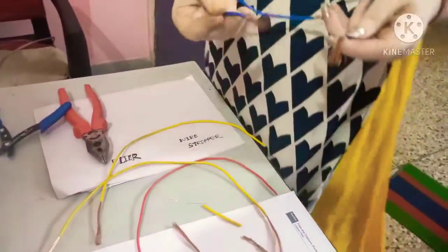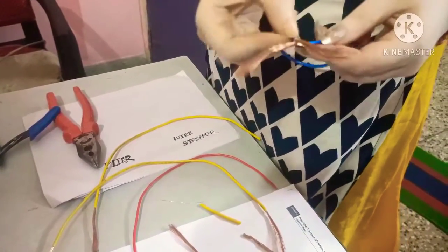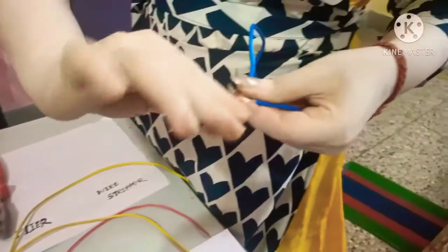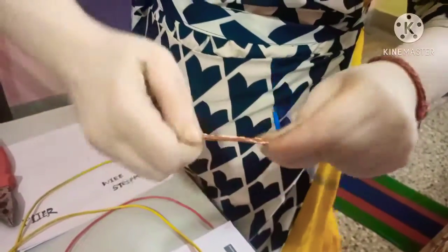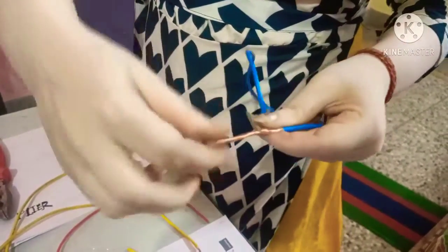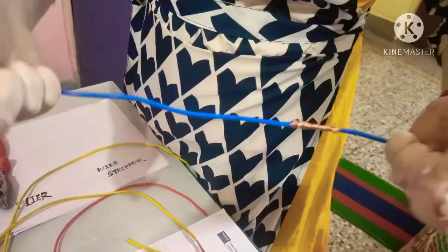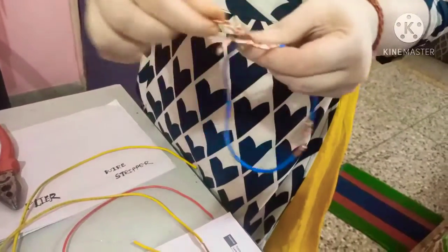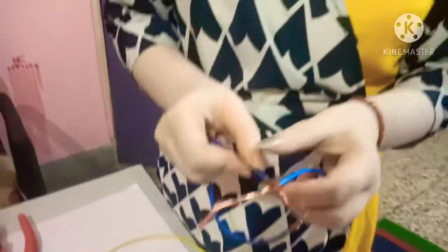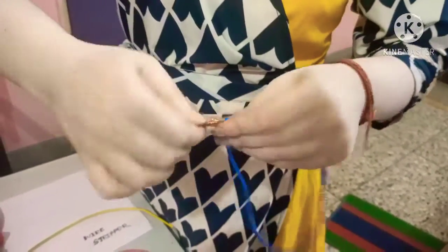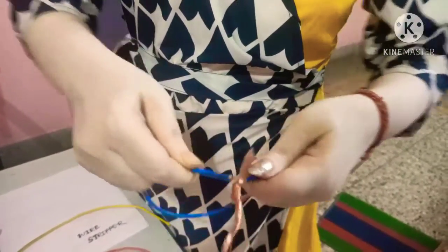So basically we usually take these two wires which I have already stripped. I am trying to join in this way. Just twist it. What is the problem in this twisting? If you are using this method during installation, if you stretch it, then see, it just opens. Whenever you are installing, you should make sure that both the wires are safely joined, so that when you try to pull it out, they don't come out. But here it is coming out.